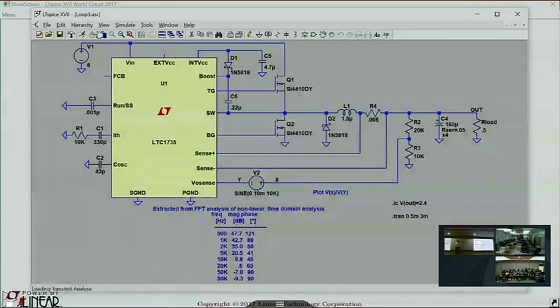And that means that all of this is just a transconductance. There's the switch node, here's the ITH, because this voltage changes the current out of the switch. You can verify that by putting a voltage source here and here, changing this voltage, and you see the current through the inductor changes.